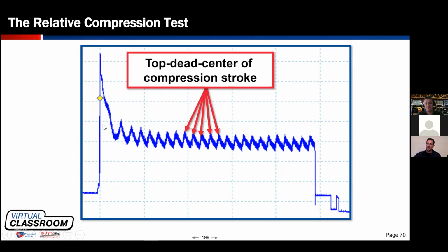When the starter amperage starts to level out and we get these peaks and these valleys, this means something to us. Now think about this. If I hit the key and the engine starts cranking over, we know of the 4 strokes, intake, compression, expansion, and exhaust, that the compression stroke puts the highest load on the starter.